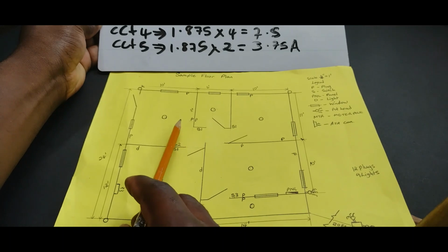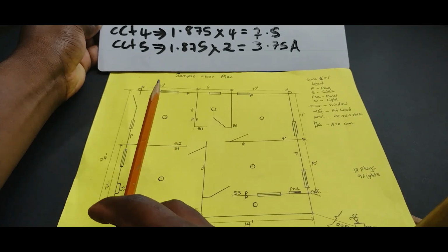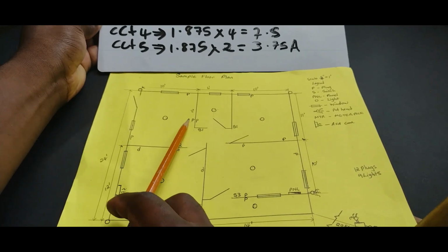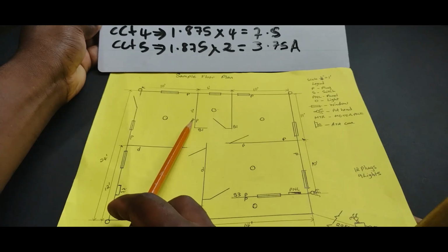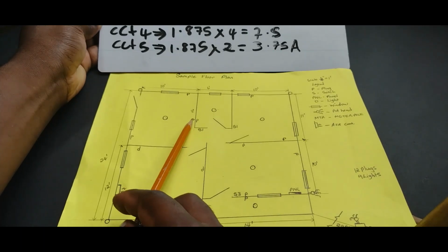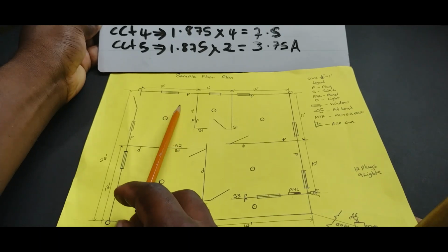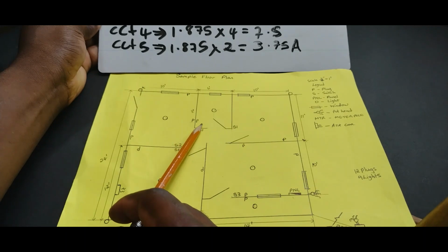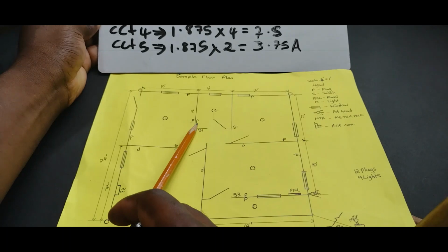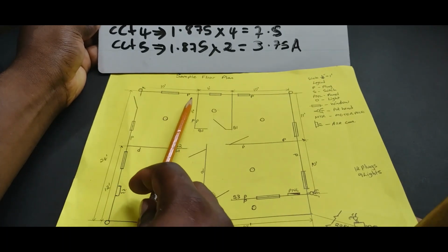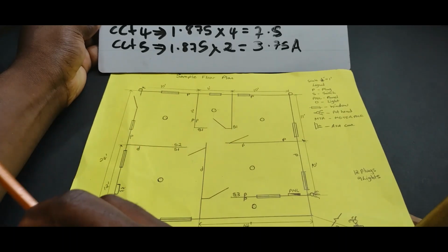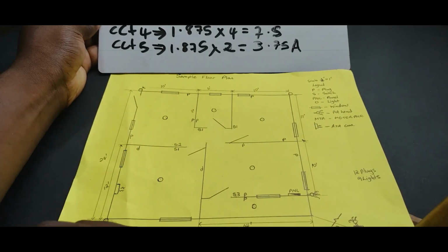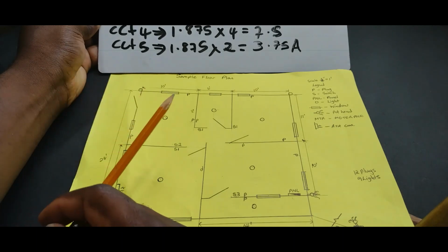Now, for the purpose of being able to switch off one area when we switch one breaker, we just put these two on one, so that when you switch the breaker off, all the counter plugs will be off. And for the bathroom, when you switch that breaker off, that plug will be off as well. Instead of putting these two on one and these two on one, so that when you switch off the bathroom circuit, the kitchen circuit will be off.